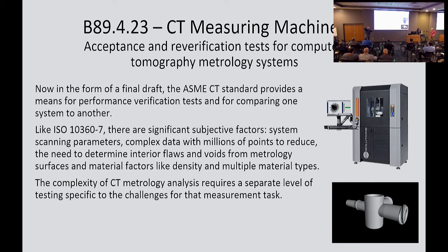With CT, take it up a notch. It's a big notch, and all of a sudden I've got my power, I've got my number of steps, I've got the resolution, I've got all these different subjective decisions I've got to make before data gets spit out. So that makes CT a little more challenging, and that's why we won't just say, oh, just measure with CT, because it'll be perfect all the time.